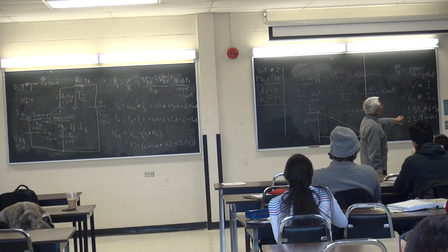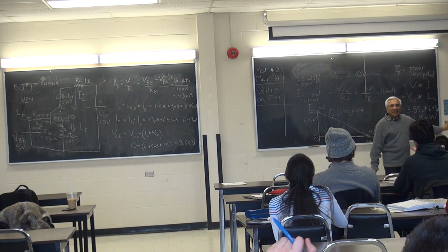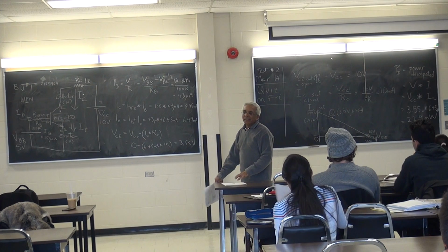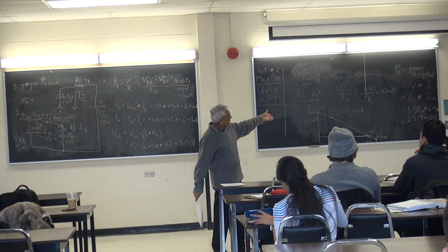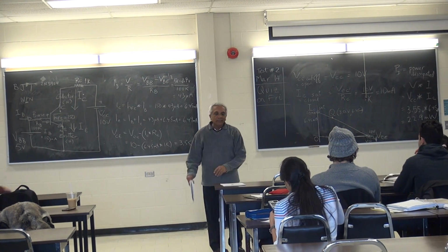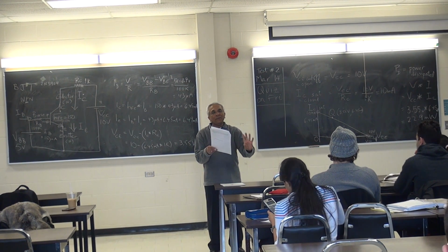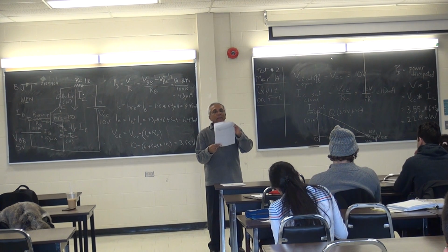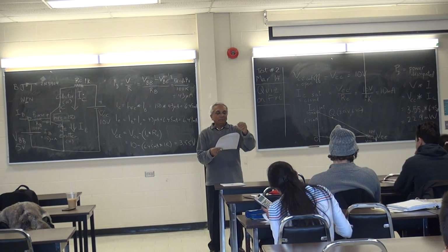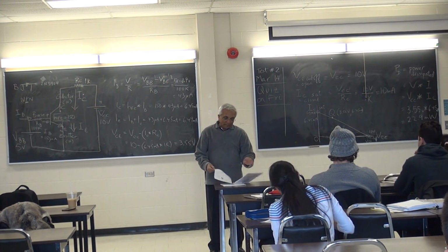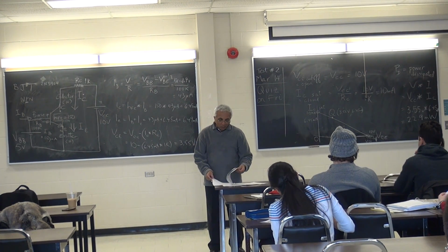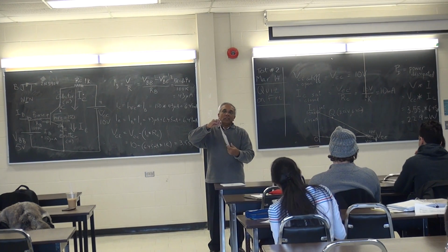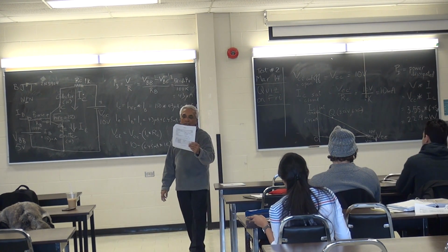Where am I? 22.9 milliwatts. Am I pretty safe? The power is not as much as 500. It's not even 100. It is about 1/4 of 100. So that transistor is pretty safe. It's not going to be getting too hot. Okay? So that's what that value is. So that's the calculation that we're going to build these kinds of circuits with in our lab this week. So let's look at the second circuit on page 12.